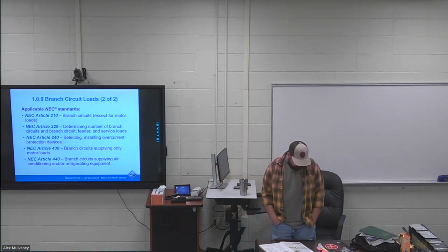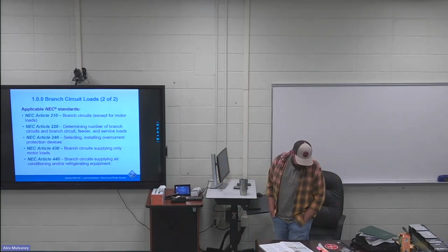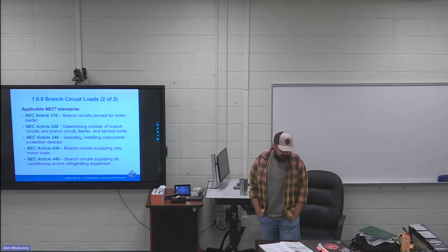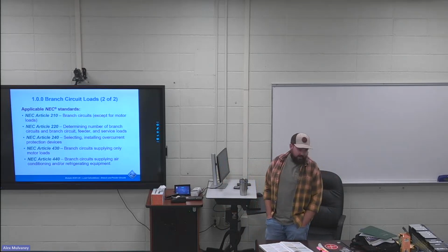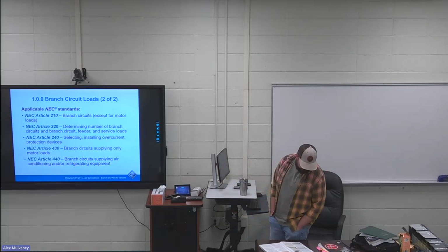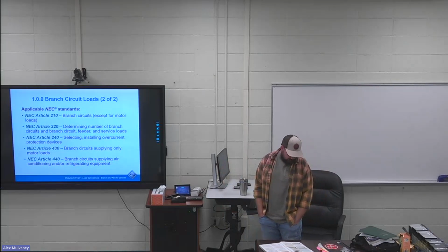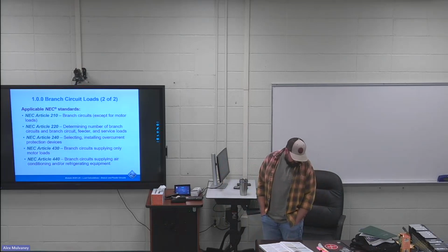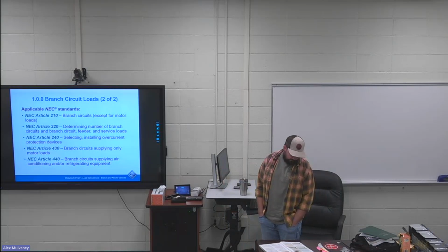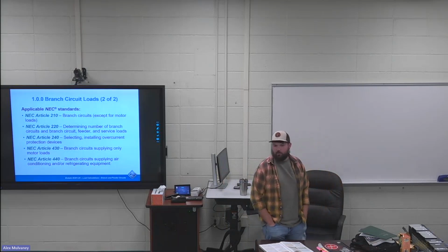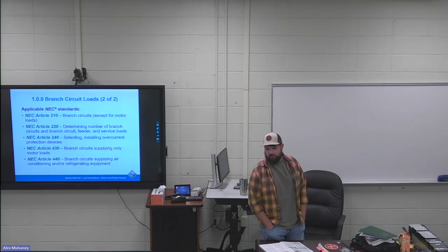Page 2. My first highlight on page 2 is the third green highlight where you see NEC table 220.12. That through the end of the paragraph is highlighted. NEC table 220.12 gives general lighting loads listed for various non-dwelling occupancies. These general lighting loads are expressed as a unit load per square foot in volt amperes. Volt amps. Anybody know what a volt ampere is equivalent to?